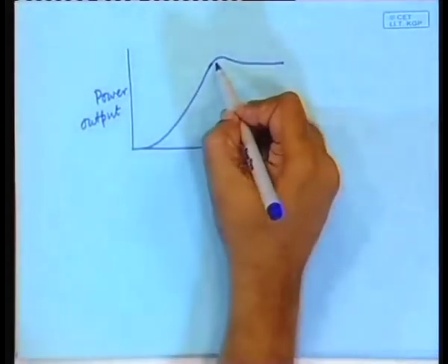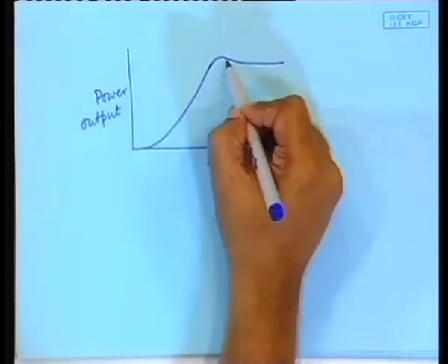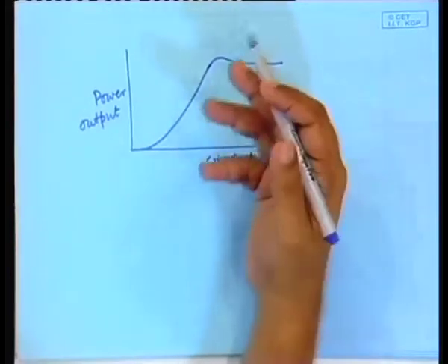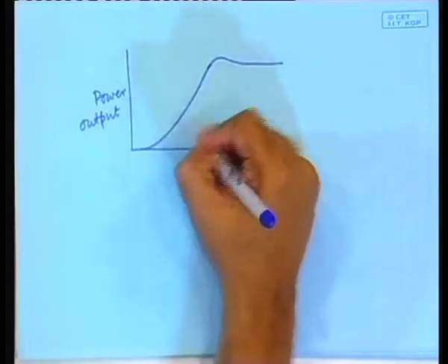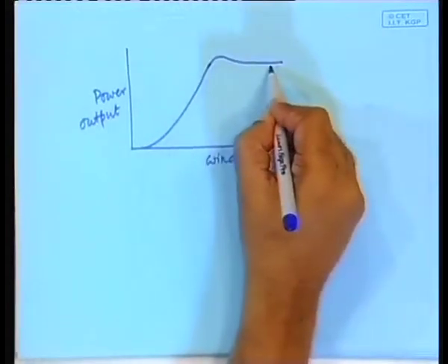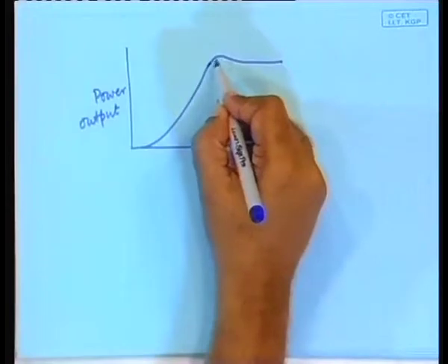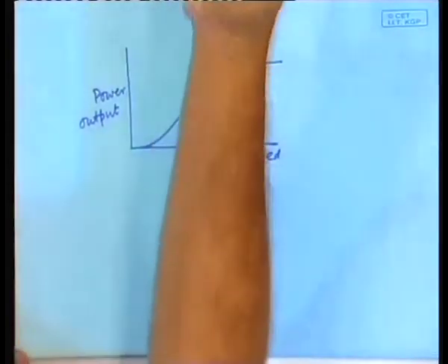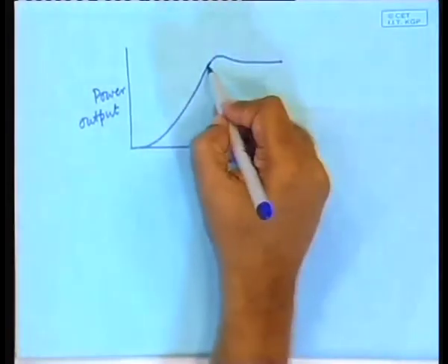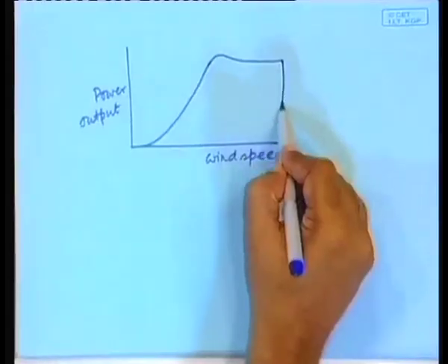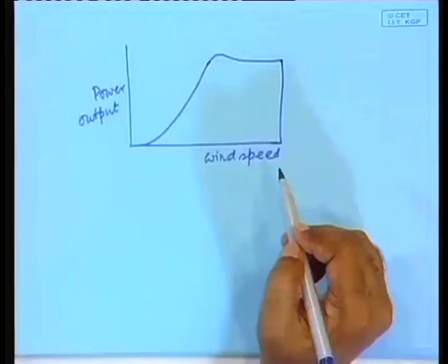Why this hump? Because this is the range zone in which you are essentially shifting from this mode of operation to that mode of operation, and there is a twilight zone where the wind contains a lot of power, but you have not yet shifted completely to this. So, if you have a passive stall, then what will happen? It will still increase for some time, and then as the angle changes much, it will fall, and at this point again it has to be completely stopped.